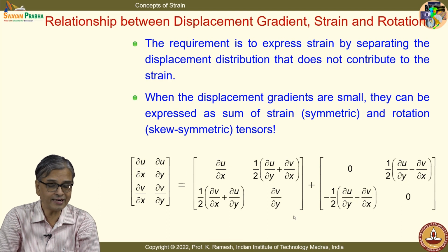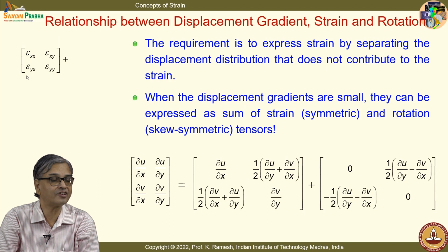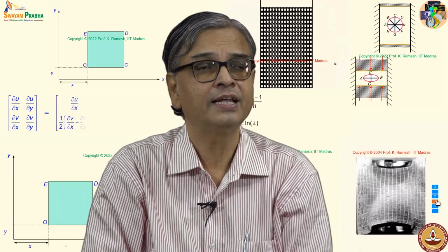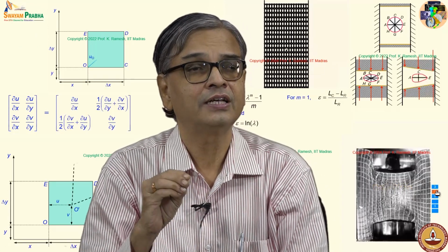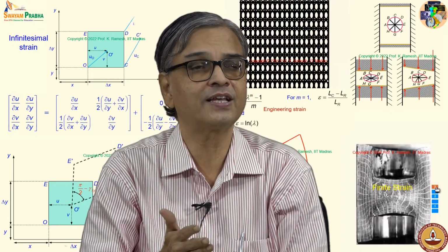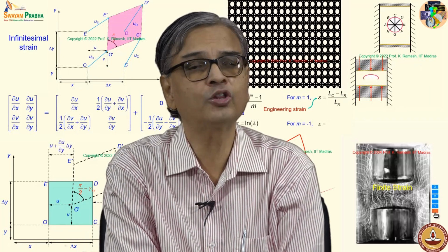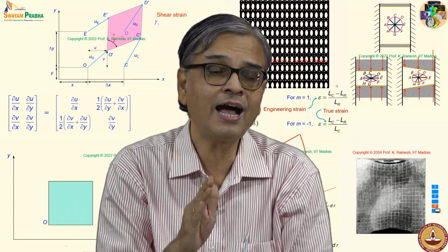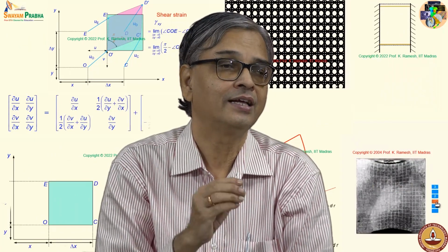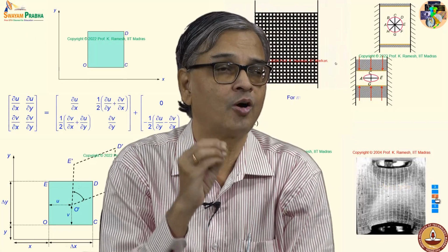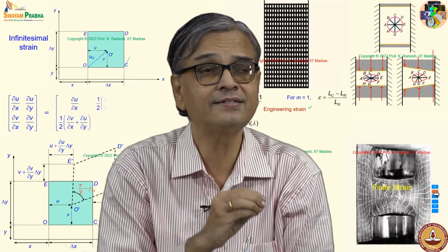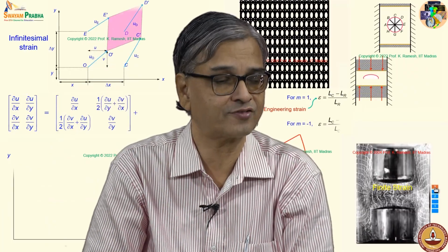So, this quantity transforms like a tensor, and you call that a strain tensor. You should know the distinction from the engineering definition of shear strain. Gamma xy is used repeatedly, and both symbols are used. When it is used as gamma xy, only one half of gamma xy is to be taken as a component in the strain tensor. Only this obeys the laws of tensorial transformation.